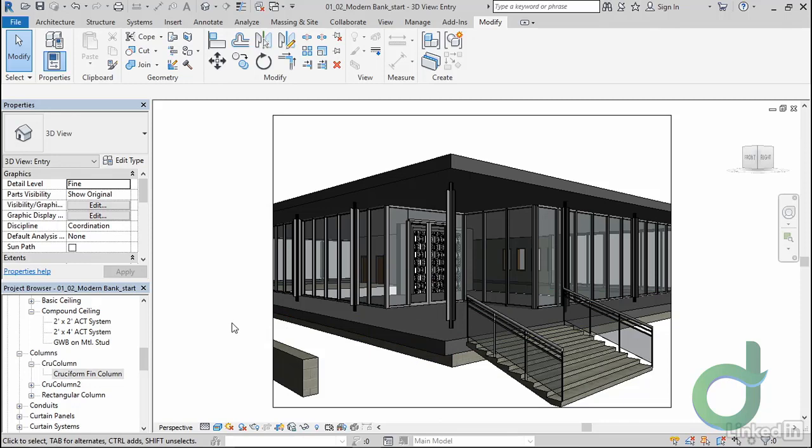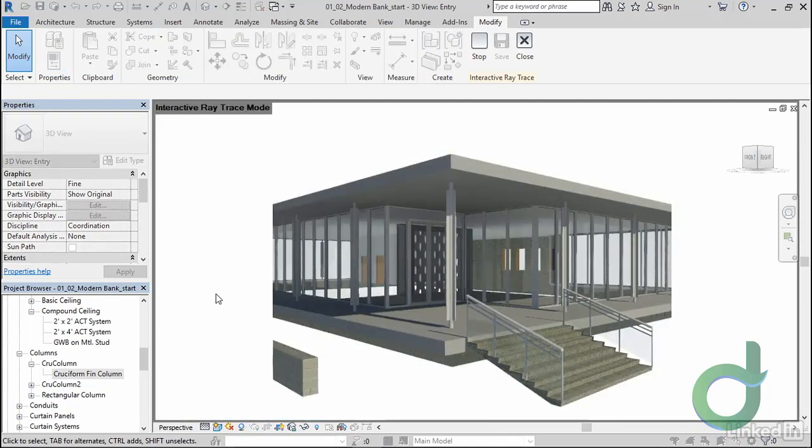As a final test, I'll do a quick render here. We can switch the visual style over to Ray Trace and see how it looks, or actually do a rendering. I'm here in interactive ray trace mode, and it's good enough. Where I'm looking is right here, this one column that's out here in the sun, clearly in view, on the slab, in the entry, in a very typical shot for this kind of building. And it definitely looks round, and I've got a nice clean joint and shadow line here, right where this steel joins. My other columns are all in shadow, so it's working nicely.